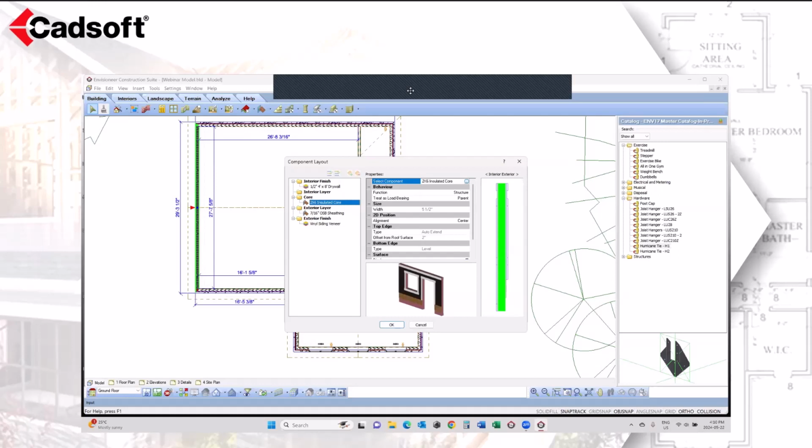In version 16, when I inserted my model into worksheet space, sometimes the lines were missing, especially around window elements. Has this been fixed? Because we're using now solids-based modeling, you'll see a big improvement and a big change when you bring your model from the model space into worksheet space. The lines will show up, and I showed you how we had those separate lines for all the different components now of the wall. Those will give you more distinction, and you'll be able to put hatch patterns to all of them.